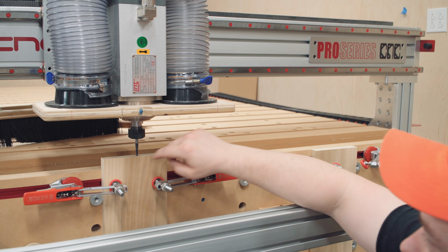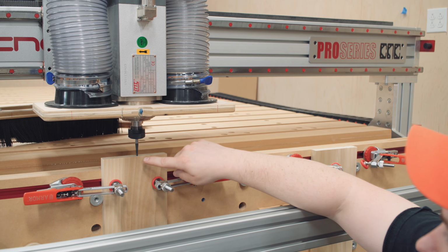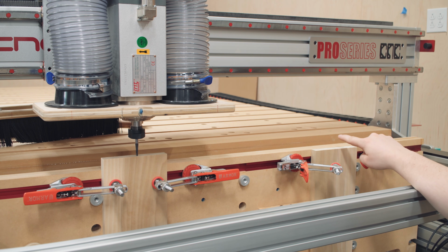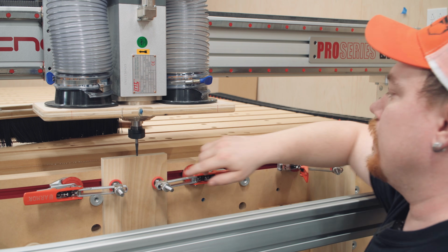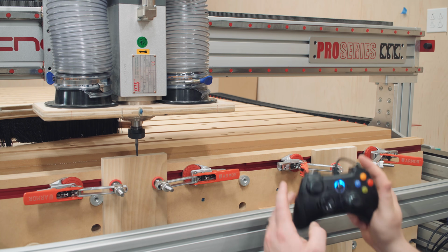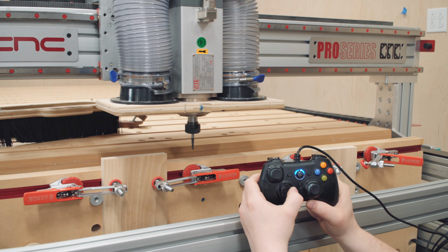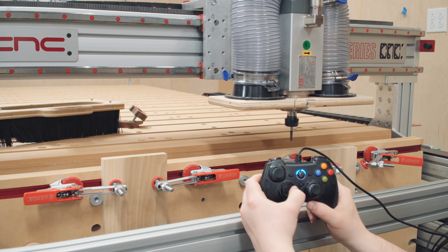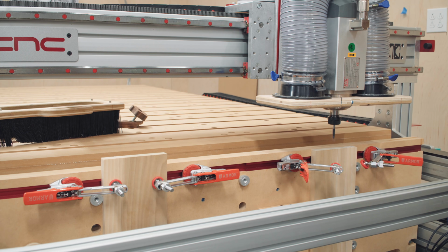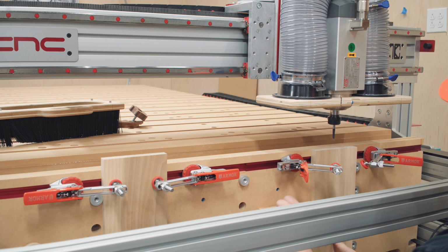Even if this is perfectly perpendicular to this, you're still going to get some unnecessary scratching up here that you don't want. So what we need is an incremental move up, move over, and an incremental move down, so we are at the exact same Z value without ever moving from our station here to set the other height. So what we can do is incremental up, the D-pad to move just in a positive X value, and then an incremental down. And now I have the Z height exactly perfect with where it was over there, and I can do the same thing on this side.